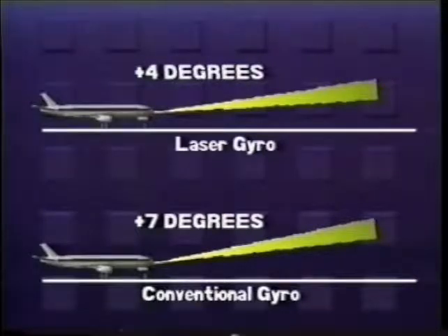Once the aircraft is in a steady climb, it will take approximately 3 minutes for the vertical gyro to stabilize and provide the radar with a correct attitude reference. As a rule of thumb, on climb-out, pilots should reduce the initial tilt setting by approximately 1 degree for each 10,000 feet of climb, or until ground returns appear on the outer edges of the scope. Once the ground returns are presented on the outer edge, small adjustments to the tilt can be made to maintain that presentation.